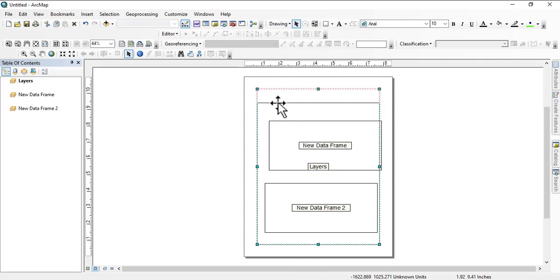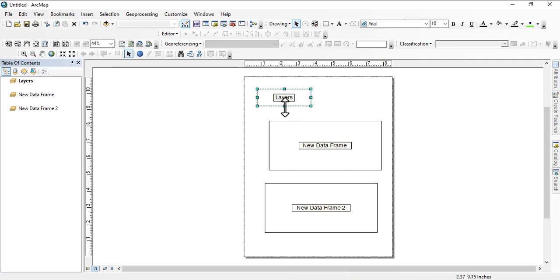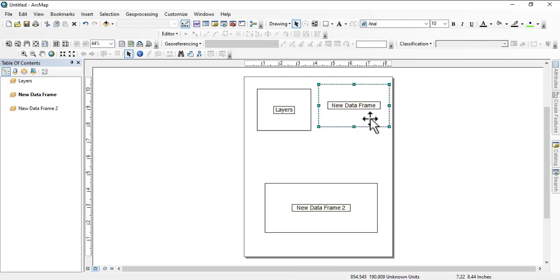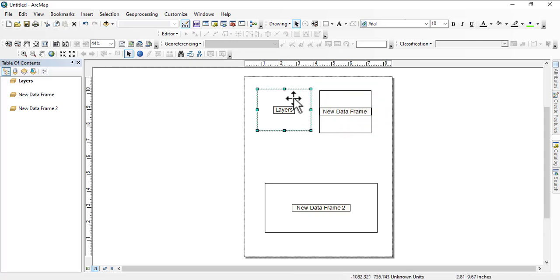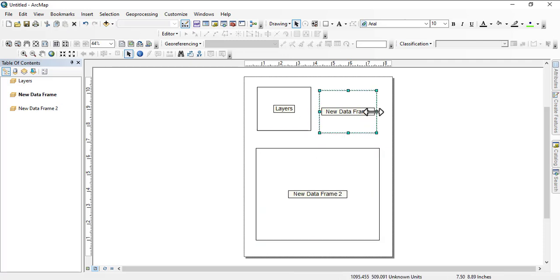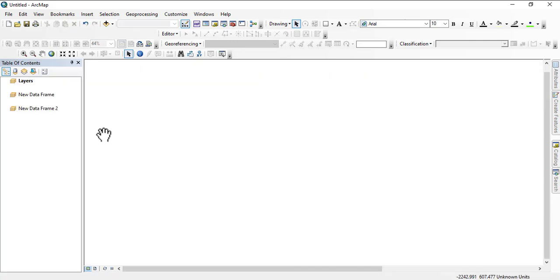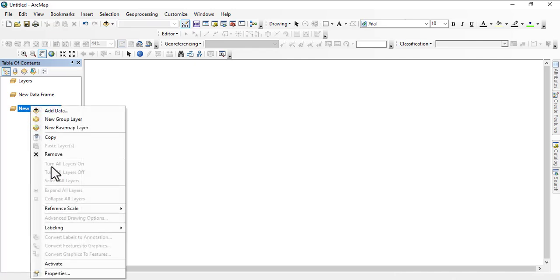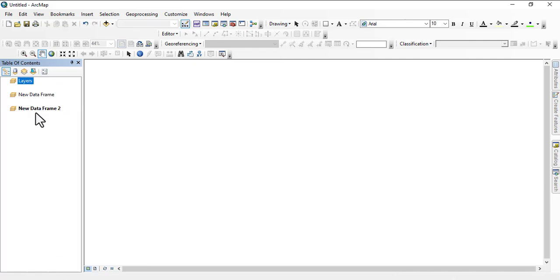So let's say I just wrap it like this. One of these will be for Nigeria, this will be for the state, because these are ideally supposed to be very small. All right, they're not supposed to be as large as your area. So you see, with this we'll be able to create a study area map. So you just need to bring in the data. Once you put the data here, it will show. So the data frame shows on layout view, but it doesn't show on data view, it shows as one. The one that is showing black is the one that is currently activated. If you want this to show, we'll come and click on activate. Right click, come down and click on activate. If you do that, you will see that it's the one showing black.